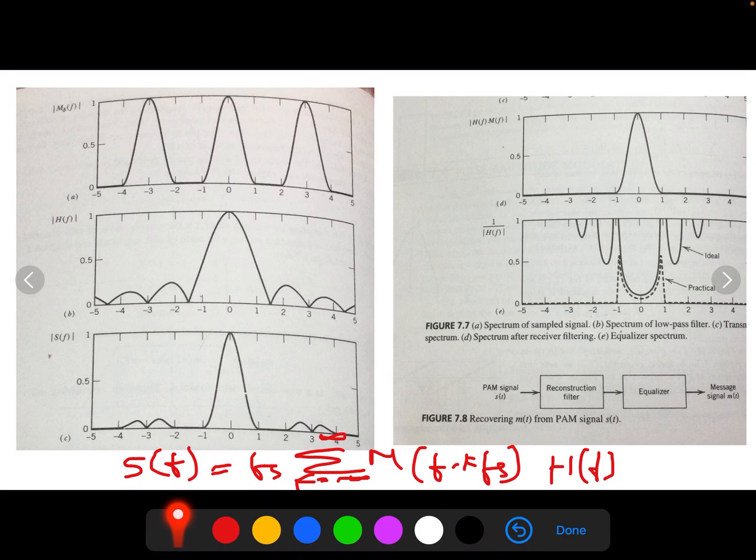This effect is similar to the variation in transmission with frequency that is caused by the finite size of the scanning aperture in television. Accordingly, the distortion caused by the use of pulse amplitude modulation to transmit an analog information bearing signal is referred to as aperture effect.